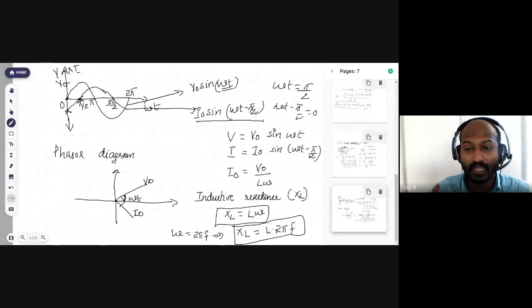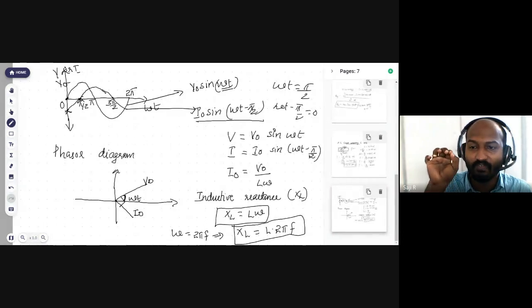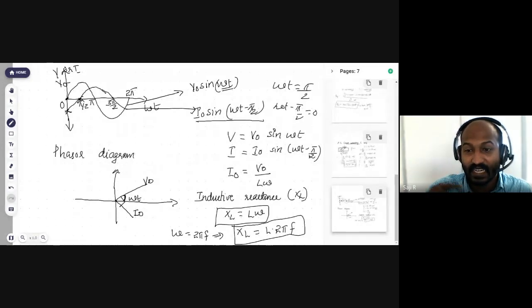Because if we use resistance, it has strong opposition against all types of current, so some amount of energy will be lost in the form of heat. But this inductor is made up of conductor, so less resistance, so no heat energy loss there. So if we want to reduce the current, we will use that inductor.